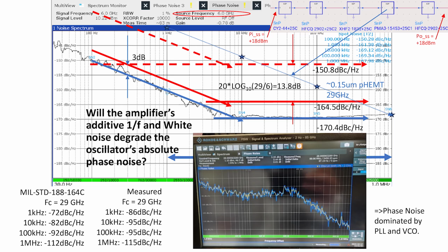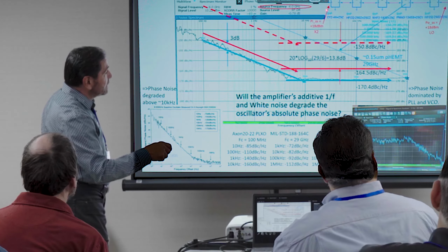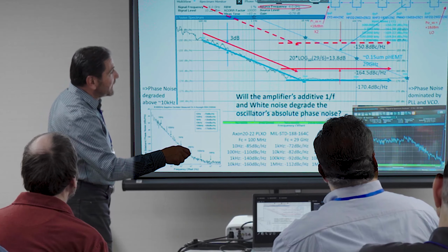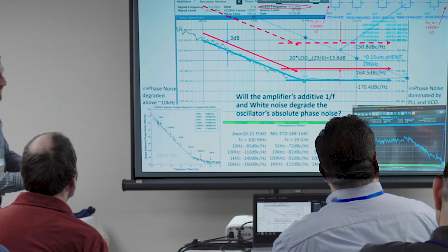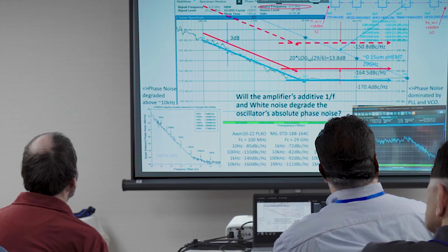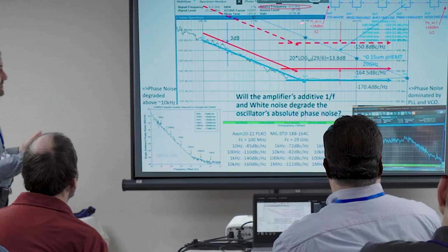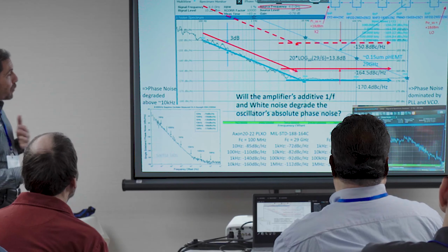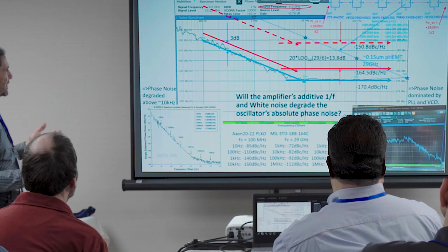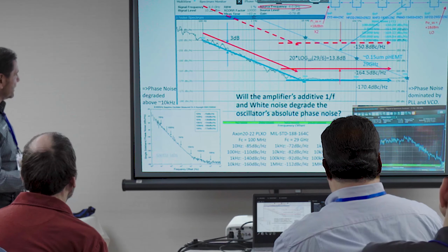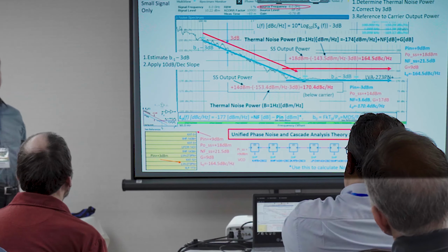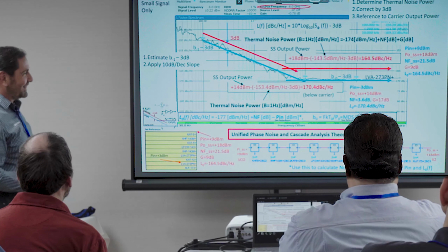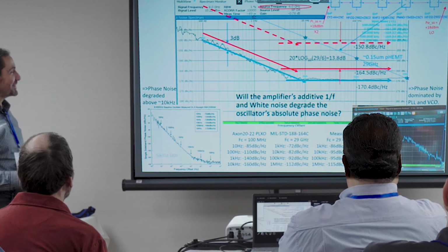So again, if we go back to our example, if we include this in it now, this goes from the multiplier output to the actual input right here to the mixer. This is our final LO. Turns out this does not affect the cascaded noise figure and gain actually, because this is about 0 dB. So we can work with this number because if you look at the noise figure, I had 21.5. It goes to 21.6.